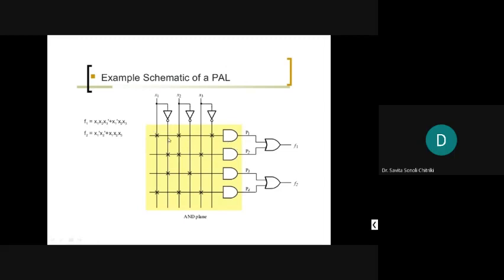So see there, this would give you x1, x2 and x3 dash through one AND gate. Then another AND gate was x1 dash, x2, x3. So x1 dash, x2 and x3 through another AND gate. Both the product terms were ORed, and finally you were getting the function f1. This concept was clear to you, right?